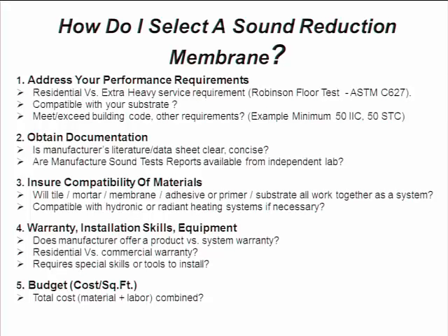Some of the membranes out there have excellent performance on sound, but if you look in the details, you'll see different recommendations from different material manufacturers as to whether you can set it with a urethane, whether you can set it with a mortar, and you need the support of the manufacturer that's making the setting material in order to guarantee that you're going to get the bond.